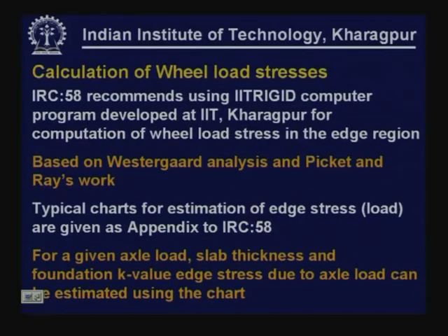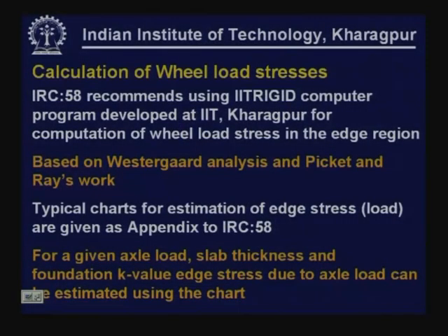For calculation of wheel load stresses, Indian Roads Congress IRC 58 2002 guidelines recommend use of the IIT RIGID computer program developed at IIT Kharagpur for computation of wheel load stresses in the edge region. As identified already, the edge region is considered to be the critical region as far as the wheel loads are concerned. So, this computer program gives wheel load stresses in the edge region because of application of single axle and tandem axle loads. This computer program is based on Westergaard's analysis and Pickett and Ray's analysis.